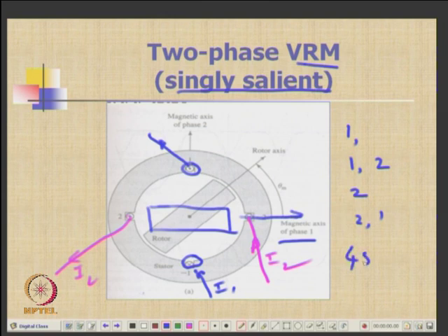So, there is a 45 degree switch step. Is it clear? In this machine it cannot be a 90 degree step, it can be a 45 degree step. It can be in this position when both are excited, then you de-energize and excite, this will come here, then you again excite both, it will come 45 degrees like that. So, you will have a way to rotate this, right.